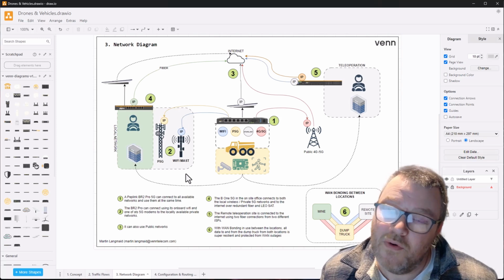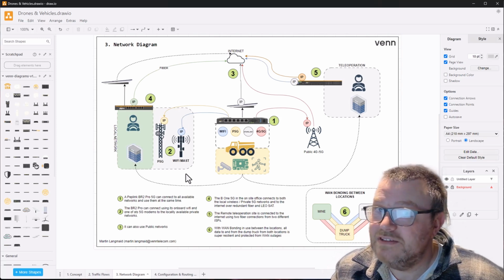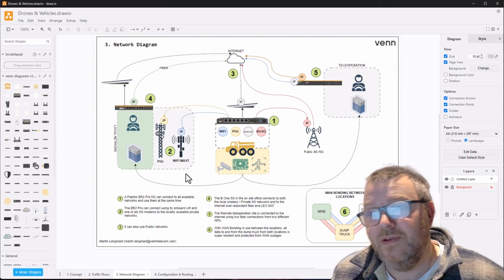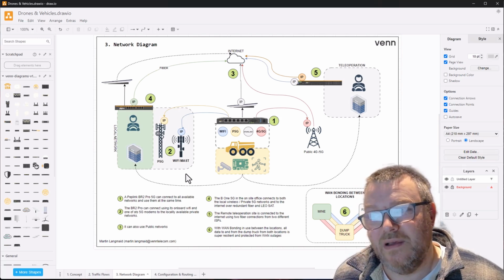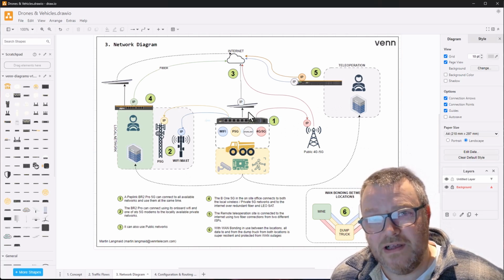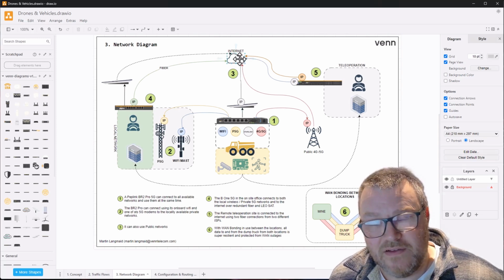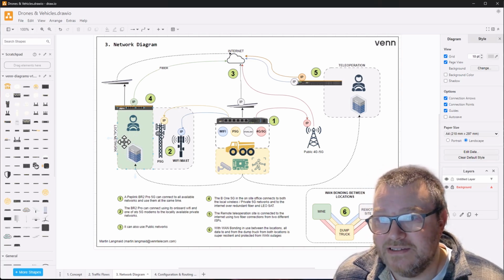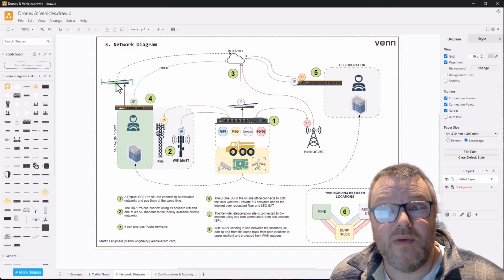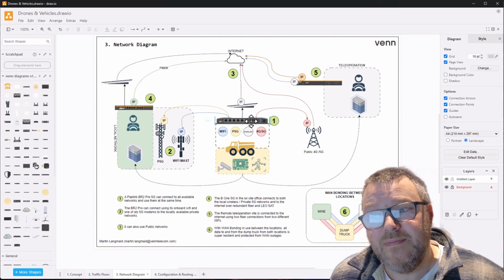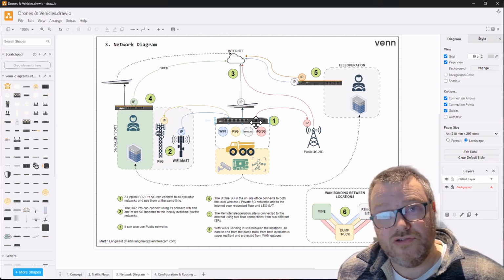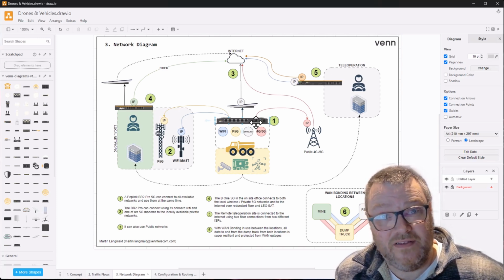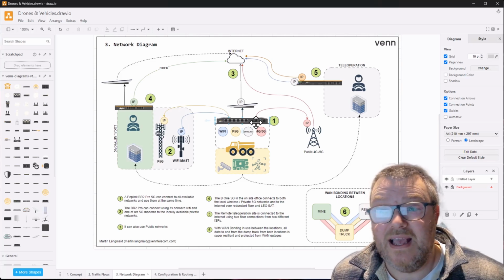But as we heard in the requirements, there are areas where we don't have private cellular and where we don't have Wi-Fi coverage. So we needed another link. And this is where the Starlink and the public cellular networks come in on the truck. Using Starlink, we can connect to the internet, of course. Now, so long as the local office also has reliable internet access, and this one does because we've got a fiber connection and we're backing it up with a Starlink, then this BR2 Pro can actually create a single logical tunnel made up of public internet connections, the cellular and the Starlink, and private connections,